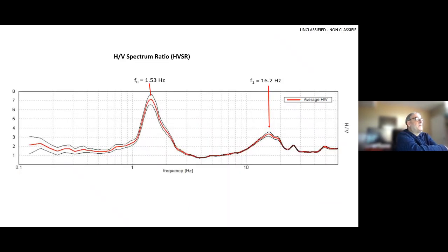So here is the spectrum from HVSR. You have a low frequency, 1.53 Hertz. That's the deepest resonance. And then you have a shallow resonance at 16.2 Hertz.